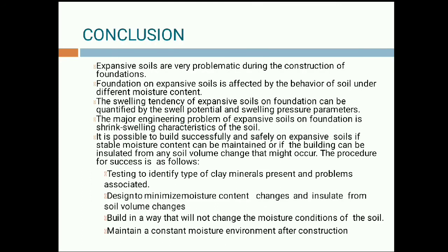Now let us see the conclusion of all the four parts which we have discussed in this series. First, expansive soils are very problematic during the construction of foundations, as we all know, because of their swelling and shrinking nature when exposed to water. A foundation on expansive soil is affected by the behavior of the soil under different moisture conditions. Based on the amount of water variation, the expansive soil will change its nature, and because of this change, the foundation will experience different kinds of load variation.